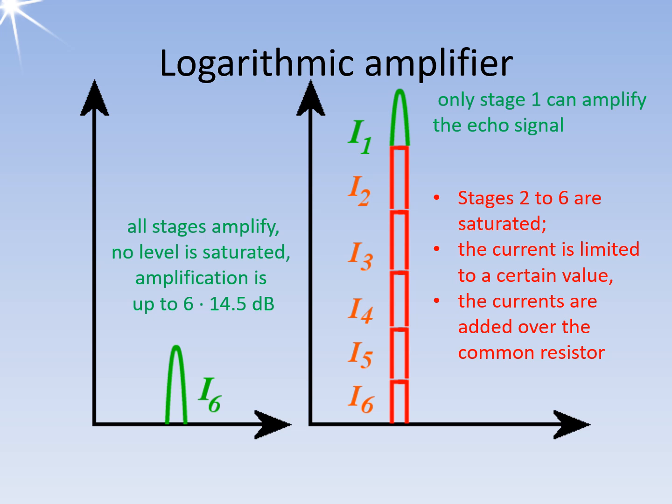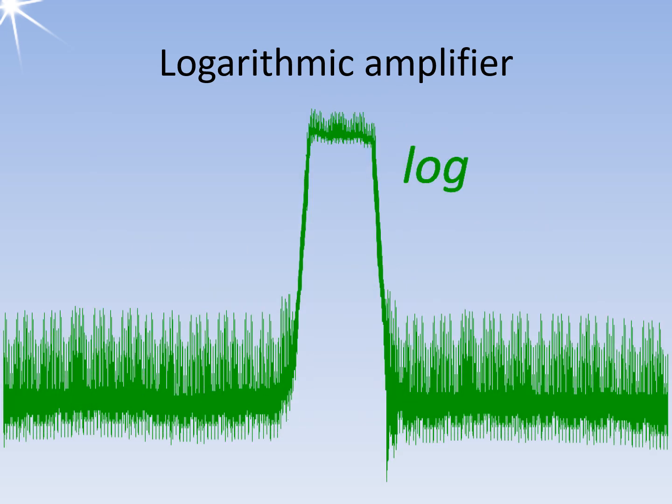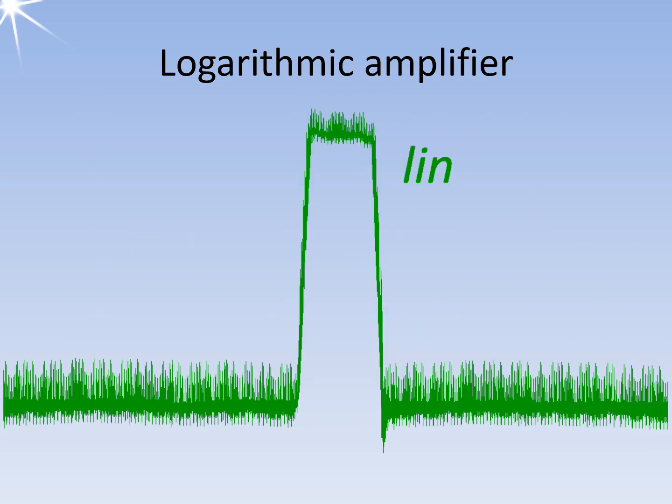The output signal is not linear to the input signal. However, the output amplitude is characterized by an approximately logarithmic function. One disadvantage, however, is that the pulse shape is changed by the logarithmic amplifier. A normally steep and linear edge rise is thereby broadened, becomes less steep, and is nonlinear. This property causes a systematic error in the distance measurement.